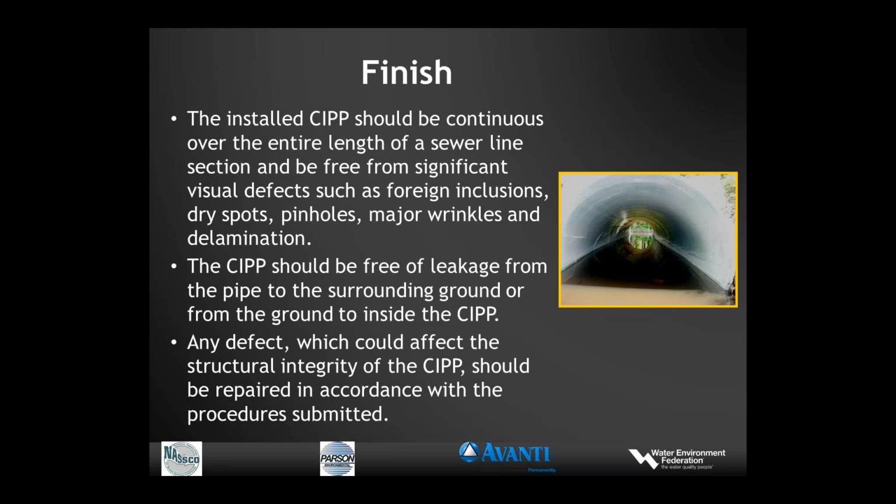So what we're after is the installed CIPP should be continuous over the entire line section and should be free from significant, keyword, significant visual defects, such as foreign inclusions, things that got stuck in the pipe wall, dry spots, pinholes, major wrinkles, and delamination.